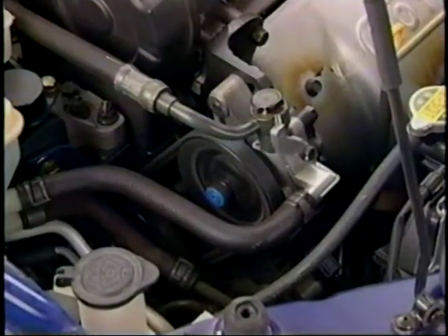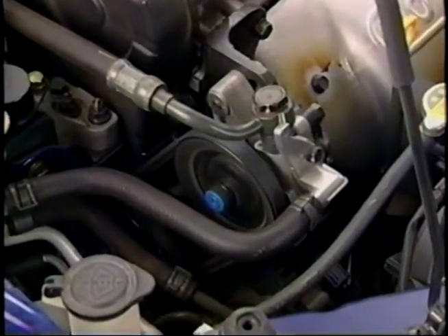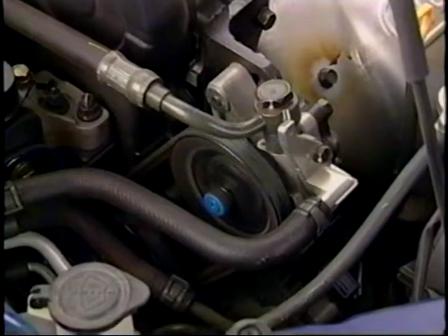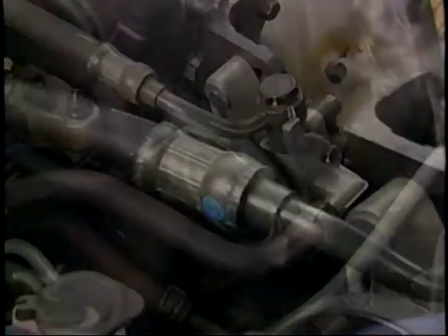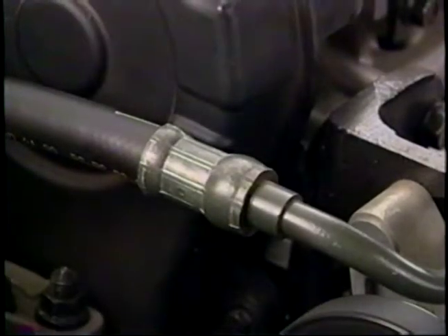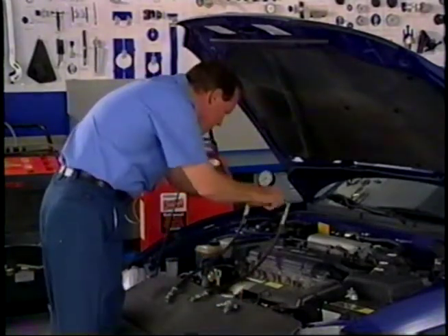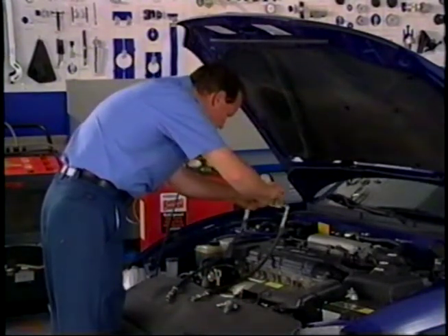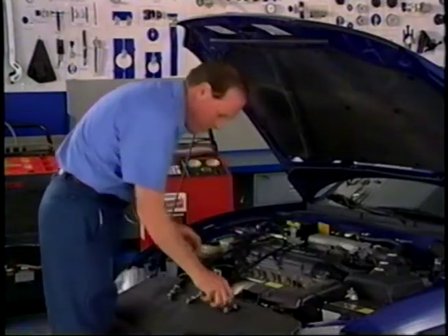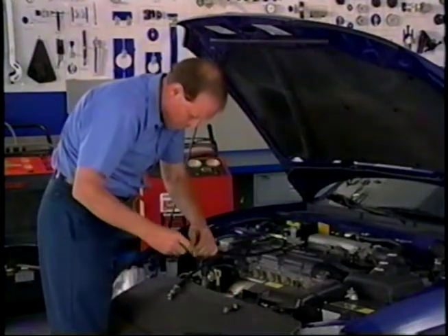Checking a power assist steering system is simple. You need to check the power steering pump, the drive belt, and the power steering hoses. When diagnosing a power steering system, use a pressure test. Pay attention to the peak pressure. The expected peak pressure is usually around 1500 psi.